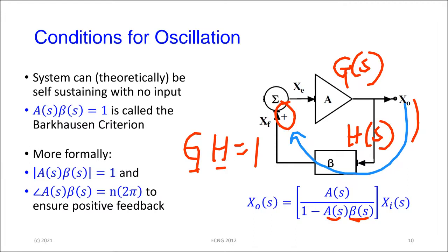So for the signal, first off, whatever comes through the feedback loop, the phase going through that whole loop has to be a multiple of 2π. In other words, if there's no phase shift, what goes out comes back in identically, that's fine, no phase shift, 0 degrees. It is the kind of thing you will get with a purely resistive network.